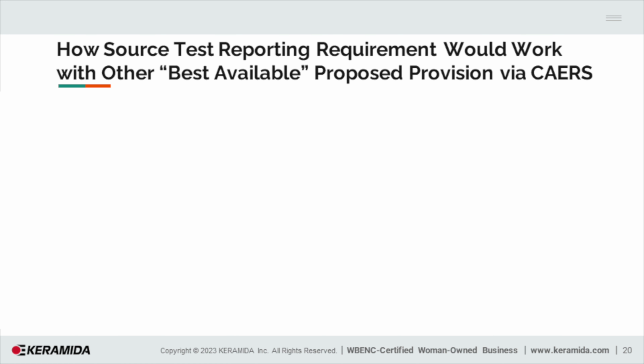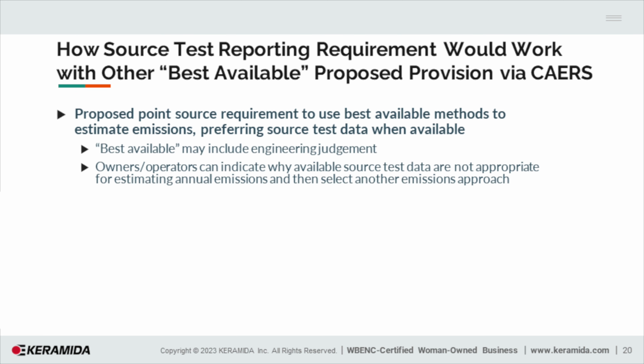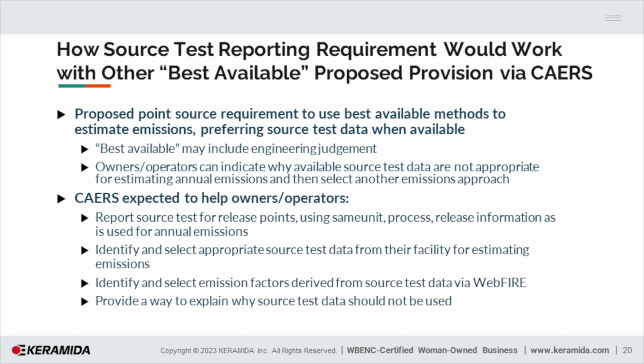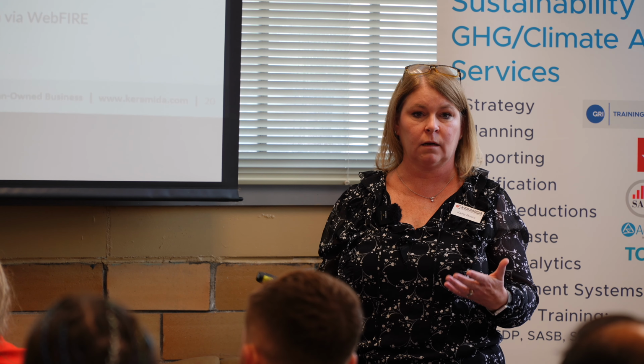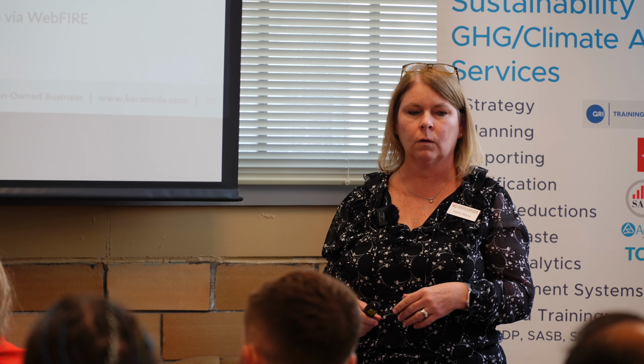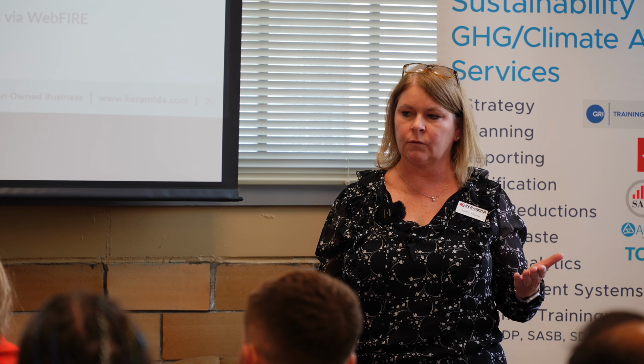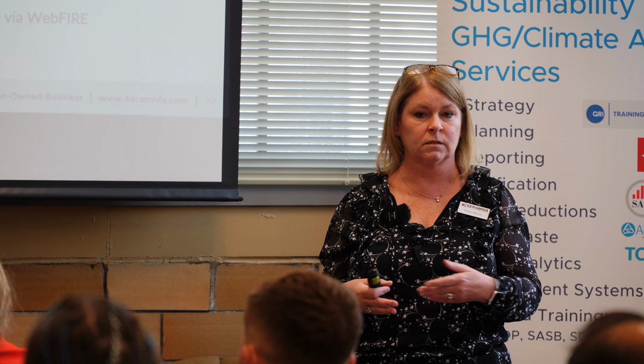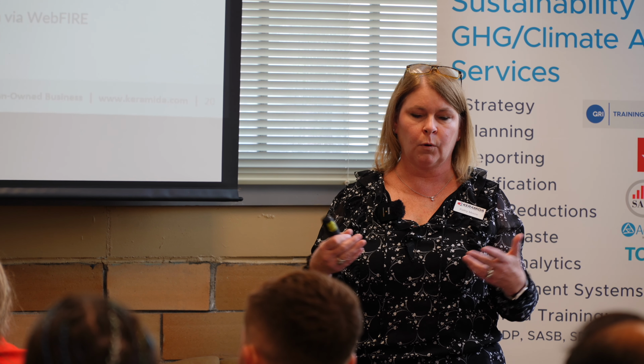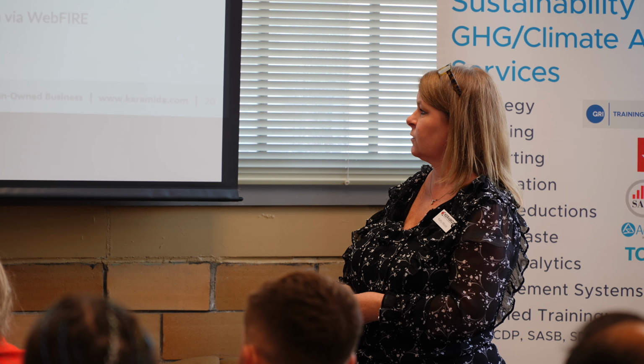So as far as calculating the emissions using your stack test data, that's going to be your best data to use to calculate your actual emissions for your site if you have that data. And again, they are thinking that this combined air emission reporting tool is going to help people with their reporting because it'll be more specific about where your emission releases are. It will give you another database to get that information. So let's say you don't know your emissions data. You can look for another facility that's similar to yours based on your SIC code or your NAICS code, pull their data, and use that as a reference point potentially.